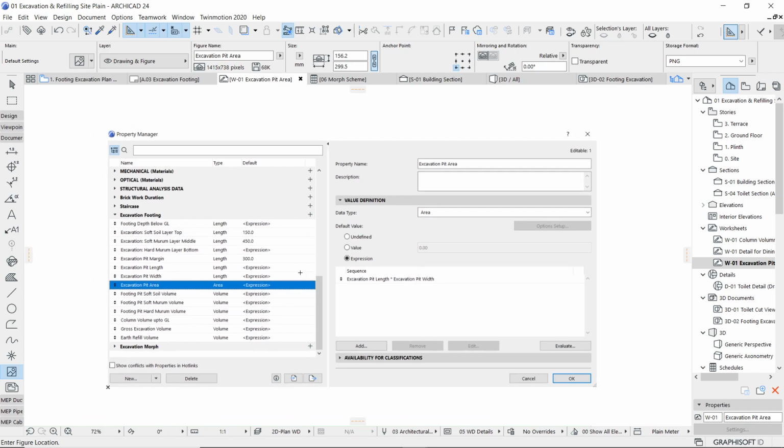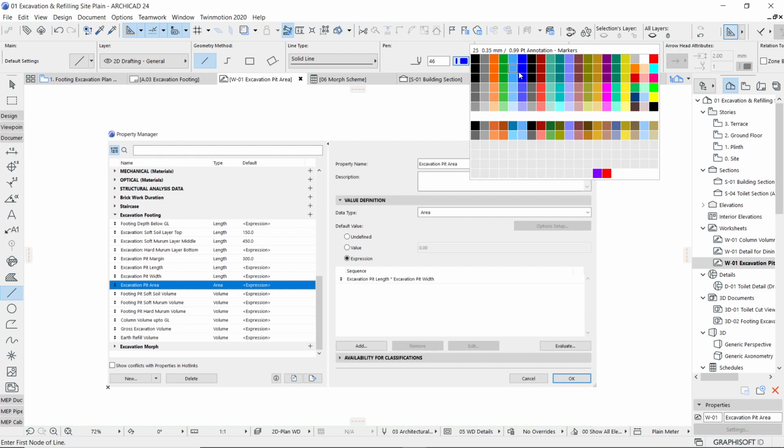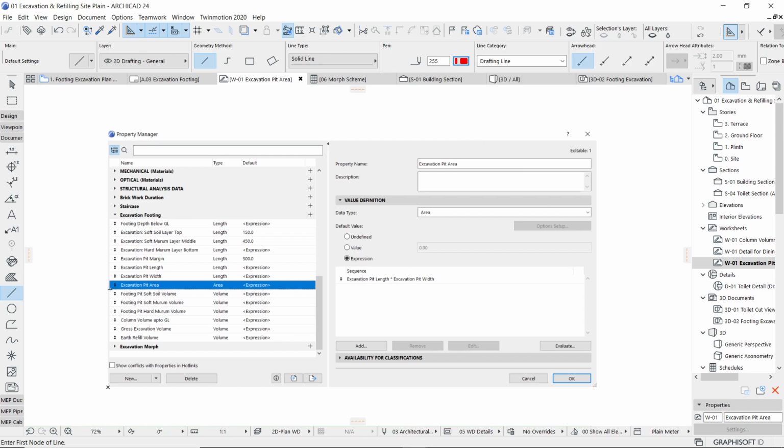almost you are ready. Now, if you want to write something or highlight something, use a proper color and line weight. I have designed a new pen with 0.5 as its line weight and red color. So I can highlight this by using the rectangle or any other valid option. Right?